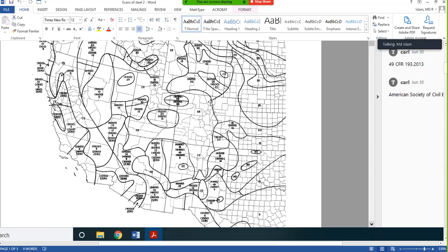You know that in Pueblo and in the hilly area, if you go to Delta, Montrose, Telluride, in that area, snow load is huge. Pueblo not so much. Colorado Springs is bigger than Pueblo. If you go to Grand Junction, there is no snow. So it changes. So we should not use this figure to design.